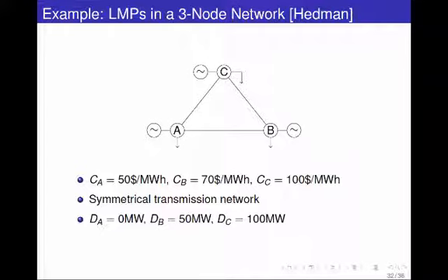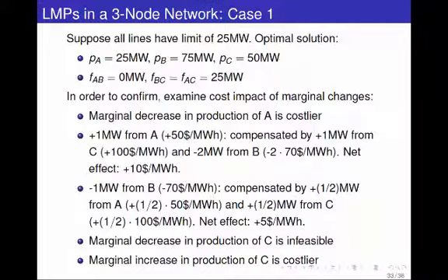Now, if both of them are producing and hitting the limits of these lines, finally you need to bring in C. So C is a solution of last resort if the lines are already at their limits, which they are in this specific example. I argue they are because I'm going to make a proof to you that is going to use local optimality as the argument, but because this is an LP, local optimality basically implies global optimality. So, okay, you don't like my solution. What do you suggest we do instead? Let's move generator up a bit.